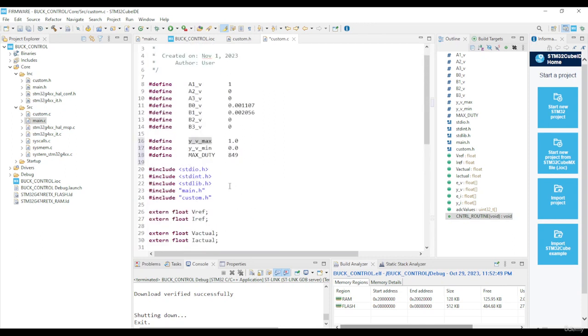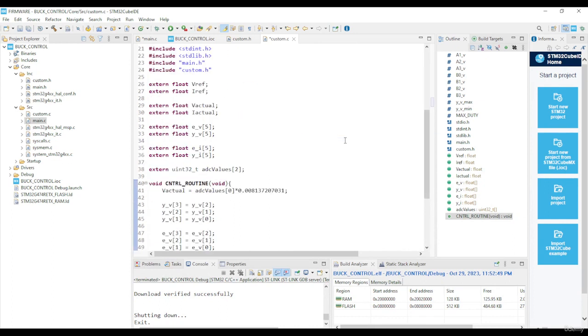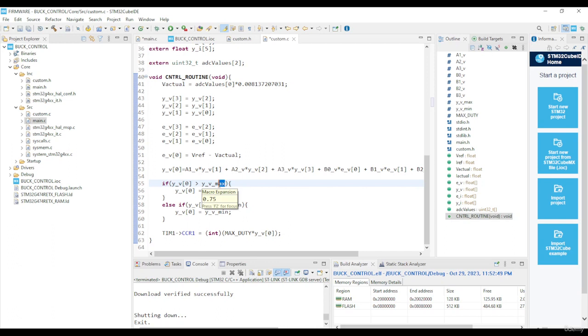So it was said to be 0.7094. I like to go a bit higher, like 0.75 for instance. So essentially it will never go above 0.75, 75% duty cycle. And that's great, because if it goes past a certain point, I believe in the 90-some percent, 95% thereabout, you're actually gonna pop your MOSFET on your microcontroller, and you do not want to do that. Okay, maybe you want to do that, but I don't want to do that. So you just want to limit that value to 0.75.